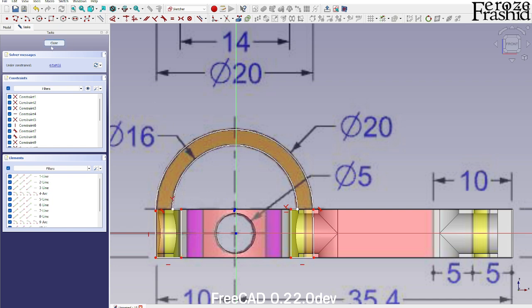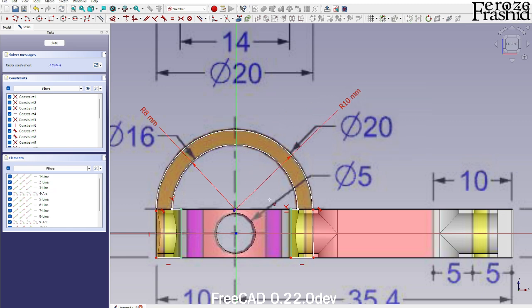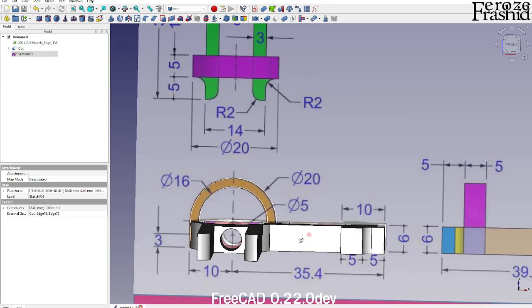That's our arch. What I want to do is apply some dimensions on here. So this is 8, half of 16. This is 10, half of 20. And then these two would be at the same point, which would be on this axis. Okay. And what else? This is moving, I don't know why it should not move. Let's make this one vertical. That fixes everything like magic.